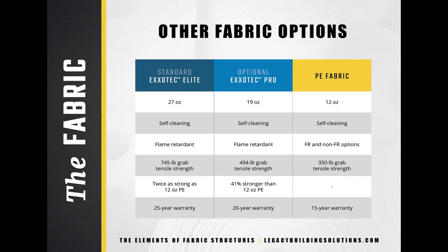Standard fabric tests include the grab tensile, strength tensile, tongue tear, and weathering test. The manufacturer should have the results of these tests readily available for each of the fabrics you are considering. But the quality of the fabric is only one piece of the puzzle. How the fabric is treated during manufacturing and installation is equally important.